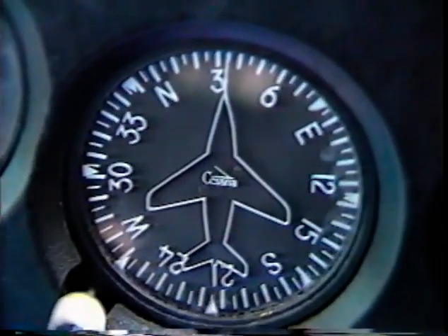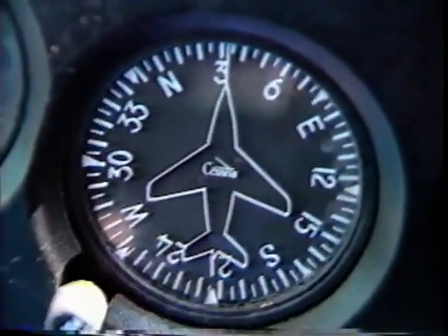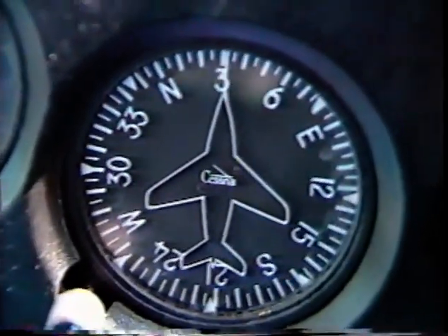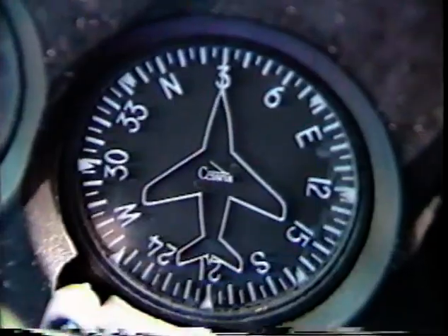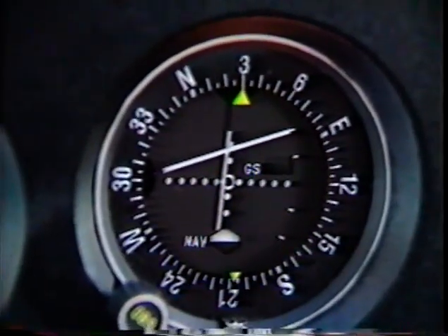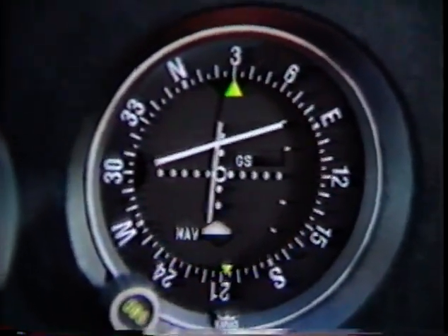On the ILS, there is some heading which will exactly compensate for wind and keep the airplane on course. It is called the reference heading, and your first job is to determine, by bracketing, exactly what this heading is. It may equal the course shown on the approach plate, or, owing to wind or DG precession, it may be something different.